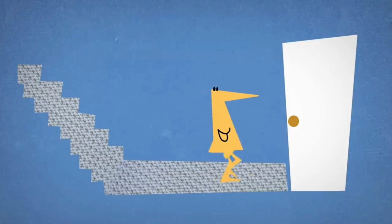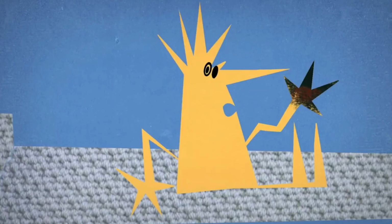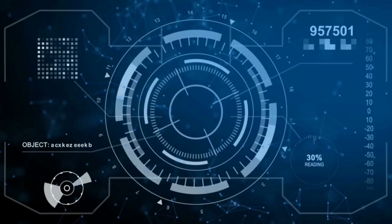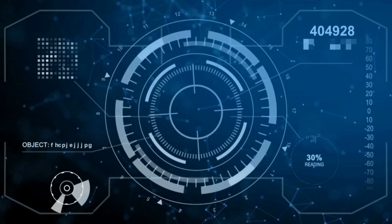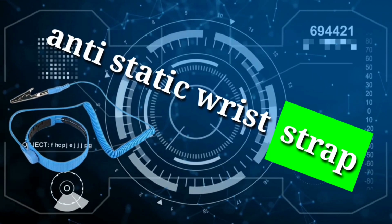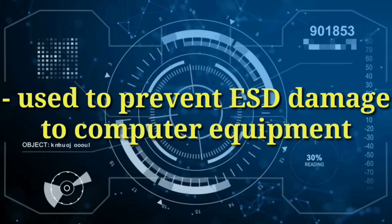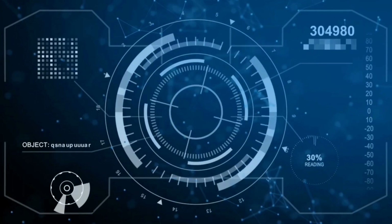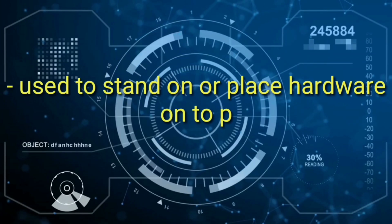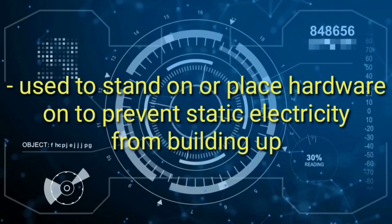Grounded anti-static work mats used with anti-static wrist straps provide the most basic means for the controlled discharge of electrostatic electricity. Examples of ESD tools are anti-static wrist strap, used to prevent ESD damage to computer equipment. Anti-static mat, used to stand on or place hardware on to prevent static electricity from building up.